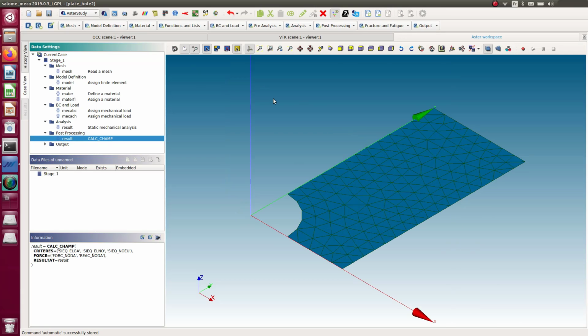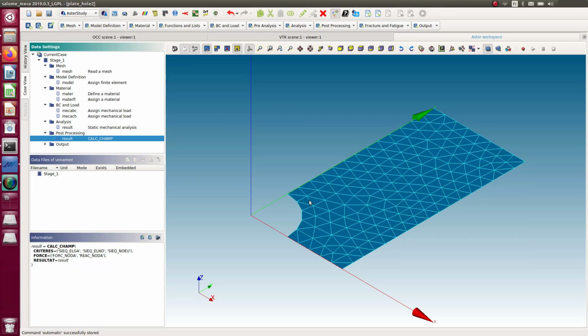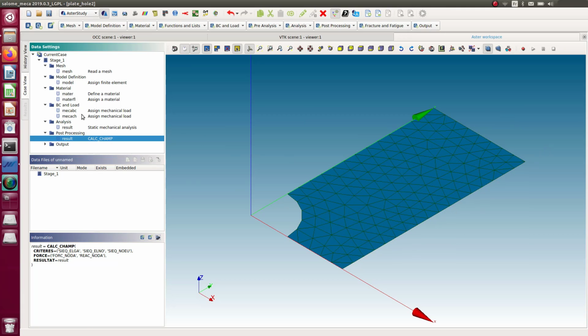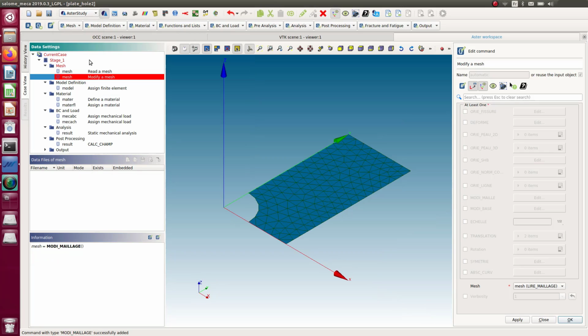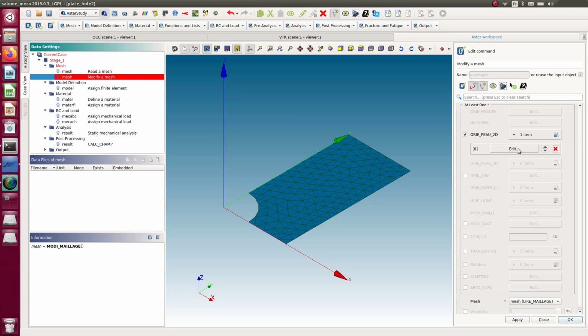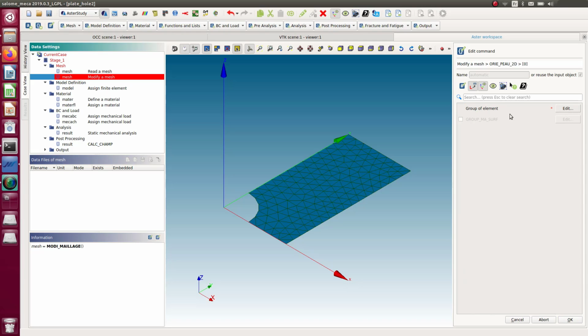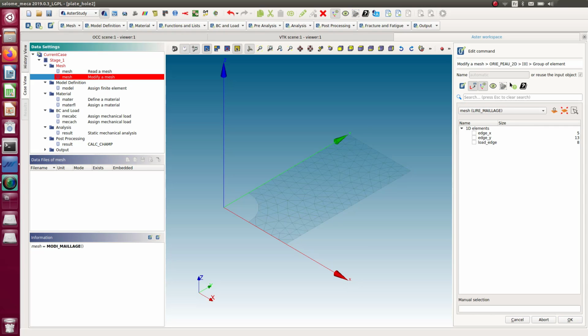Click on OK. And there's one more thing I may need to do, because if I solve like that, it might fail. I need to add something here called the orientation of this edge. So when you apply pressure to an edge, you need to apply an orientation to this. So I think it's this option, orientation PO 2D. Anyway, if you don't do it when you solve, you'll have a red sign. It will tell you that you're lacking this. So generally, that's how you know about it.